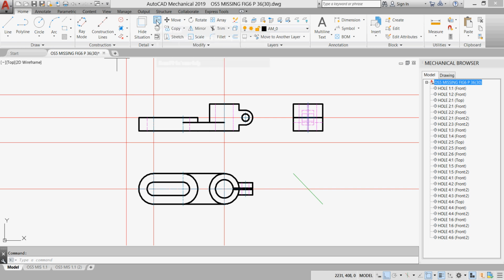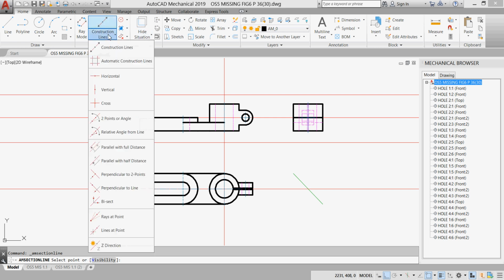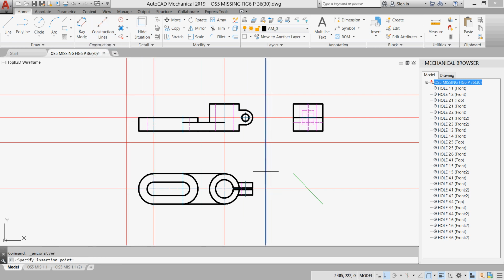Sorry, we didn't do that one. Just go back again. Take a little bit out of the cutting plane. First cut will be from here, there. Enter. Now the label of my section. This is D. I want it A, so I click A, capital, enter.